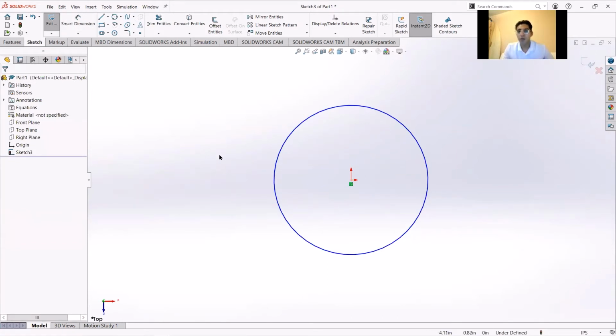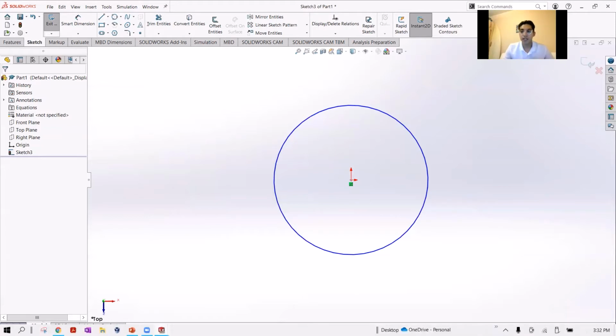But another thing that I want to let you know is by default, and I do this constantly, I'll forget to set my units. So right now it's in inches. By default, it starts in inches, but it makes it easier to work in millimeters, especially because on the 3D printing side, it is in millimeters.